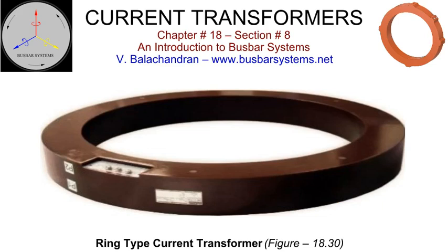All current transformers in the run of the isolated phase bus are bar primary, ring type. This is primarily dictated by size of the conductor and very high fault current. Current transformers installed in the isolated phase bus are clamped to the enclosure in 4 locations along the circumference. These are essentially low-voltage current transformers, with the major insulation being provided by the air column between the inner surface of the current transformer and the outer surface of the conductor. The diameter of the current transformer is large.